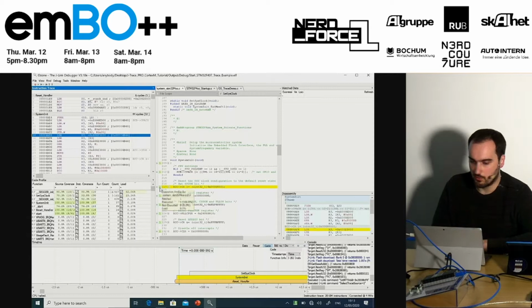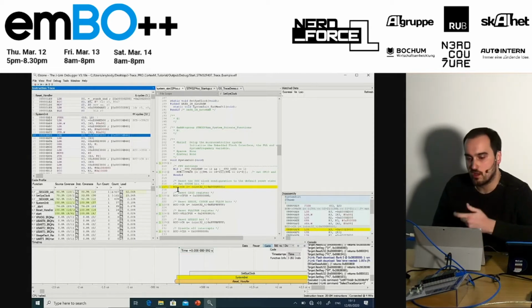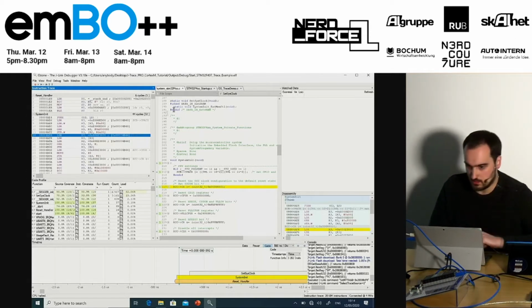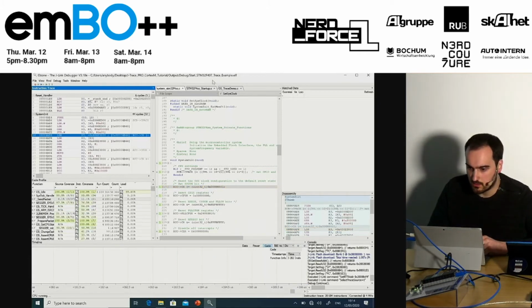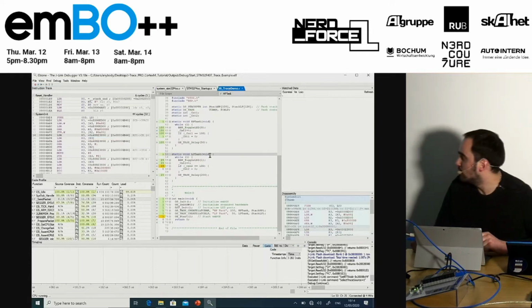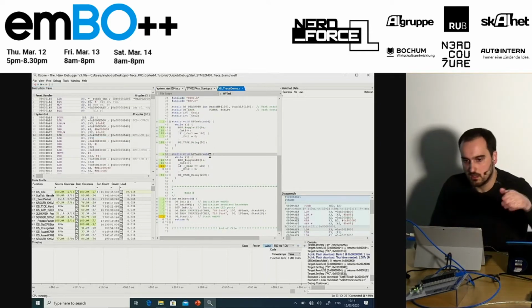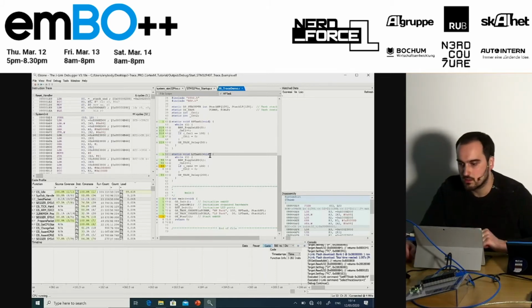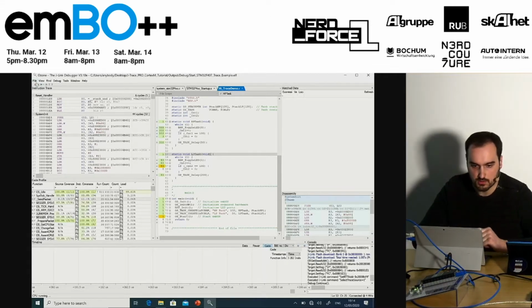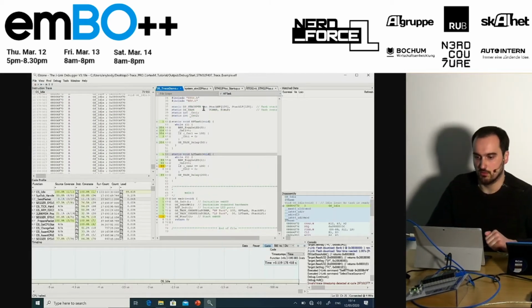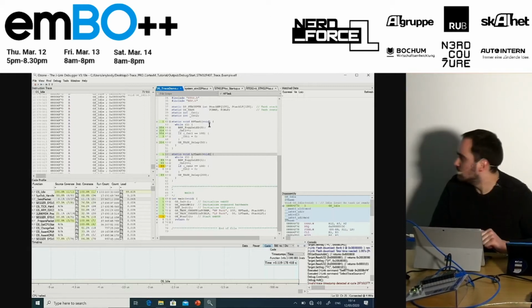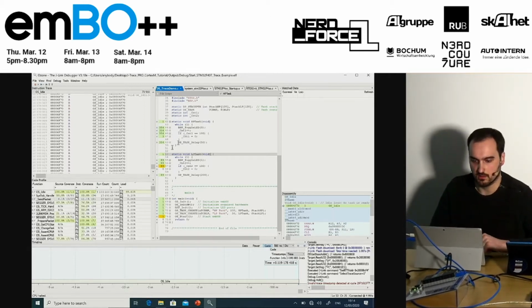You see code profiling here, so you know how often which line has been executed, has it been fully executed. Let me just let it run for a while, and you will see that the counters, where is it? Here you go. They also update live, so this is not buffered or anything. This is streamed over the USB 3 cable here, shiny blue one, and we analyze this in real time. If I hold it, it will hold exactly at the number where we, okay, we jumped now to another section of the code, but here we were before. So these are the counters that you can use here and analyze your software.